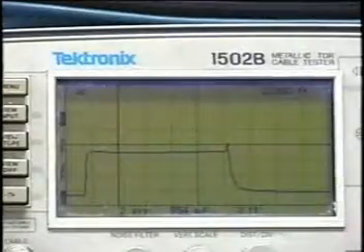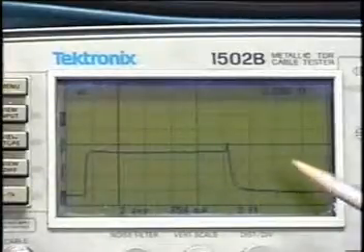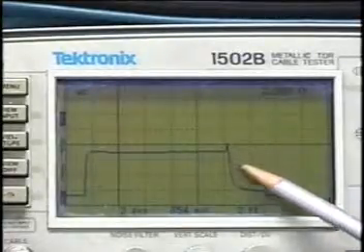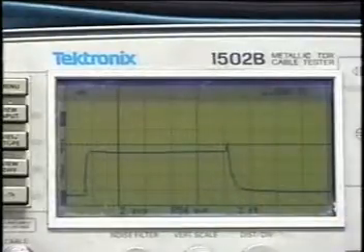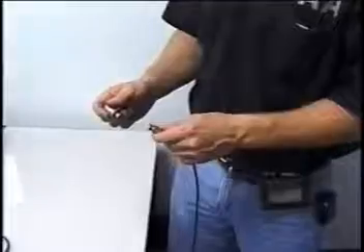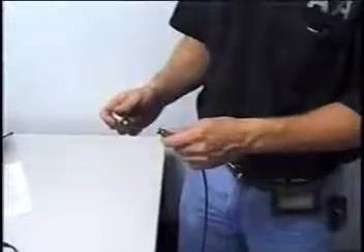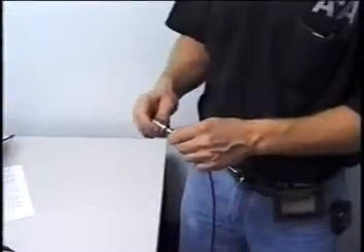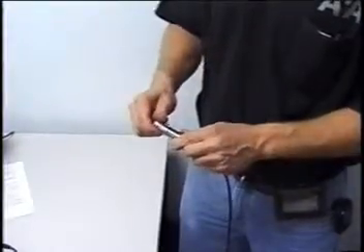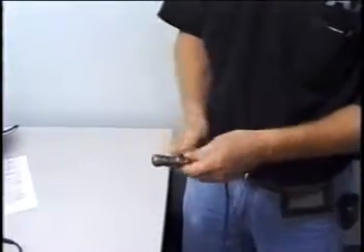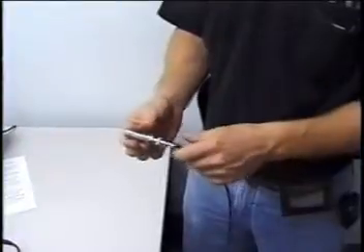With practice, you can learn to use more of the machine's features and also learn to recognize different waveform reflections. As a general rule, shorts in the cable are shown as a downward reflection of the test pulse, while opens reflect upward. Connectors, including the adapter cable connector, may appear as blips. Other faults such as wire damage, improper splices, even the presence of water can be identified by the shape of the test signal's reflection.